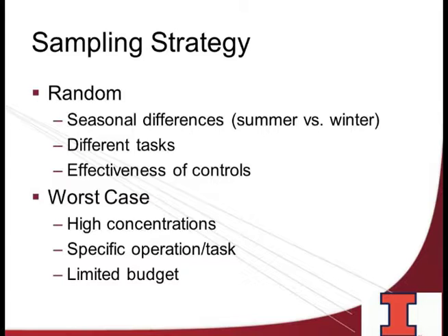Over time, local exhaust systems will end up losing some of their efficiency, and with that, you may end up losing some of that capability of pulling that material away from the individual's breathing zone. And for the purposes of personal sampling, the breathing zone is considered to be a 2-foot radius around the head.